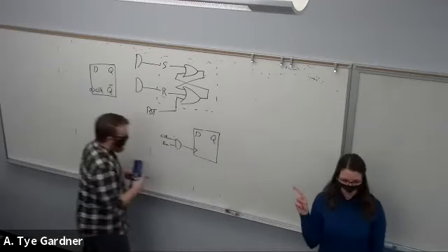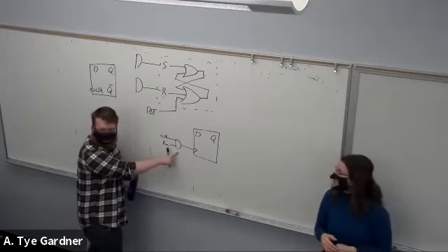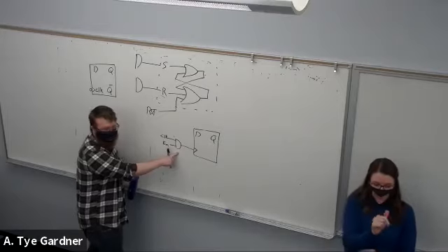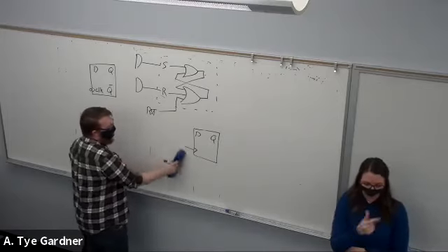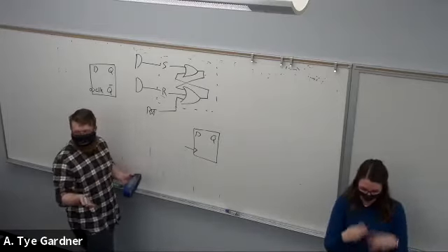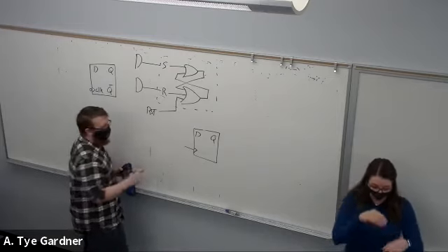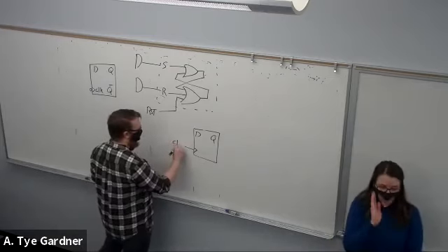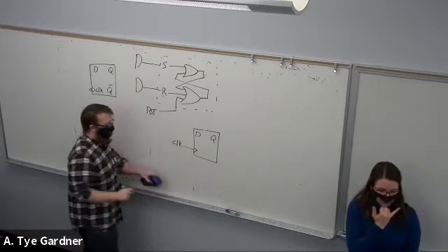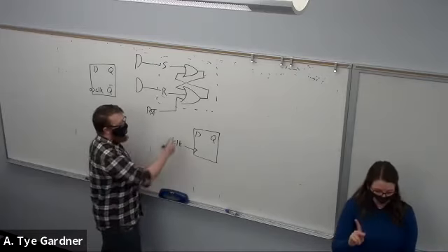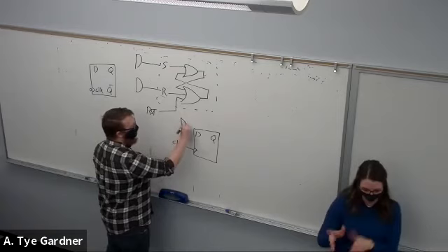We don't want to use what is called a gated clock. Gated clocks are a problem. In fact, VHDL will throw you an error if you do this. Well, at least a warning. It'll say warning, gated clock. So we leave the clock alone, and instead we come back to our old friend, the mux.